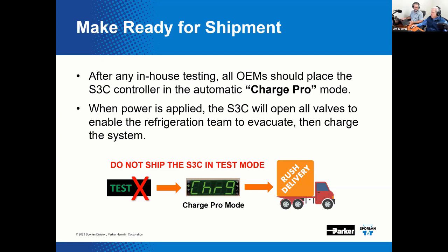So if they ship out in the test mode that the OEM was using, which does happen, it just thwarts the functionality of the control, and prevents easy evacuation of the system, and continued process. It's extra steps in the field where there is, as we already discussed, very little time to do that one day turnaround they're trying to achieve. Very little time for any extra steps. And the cases will automatically go into the so-called refrigeration mode once the pressure transducers are exposed to approximately 5 psi.